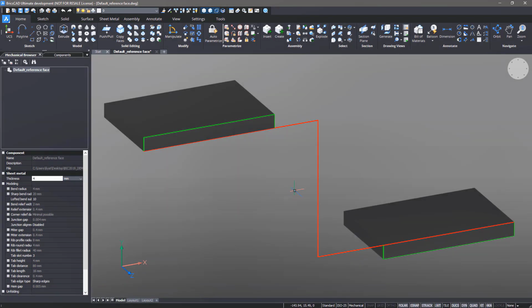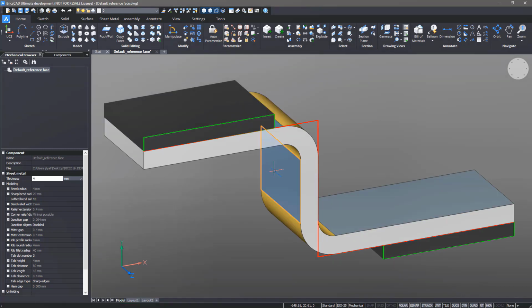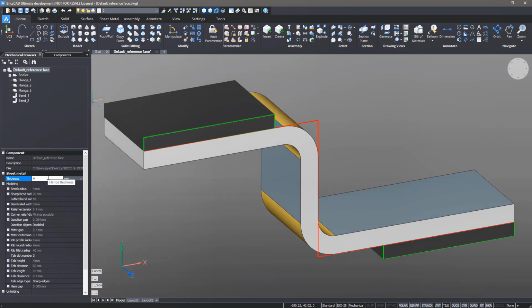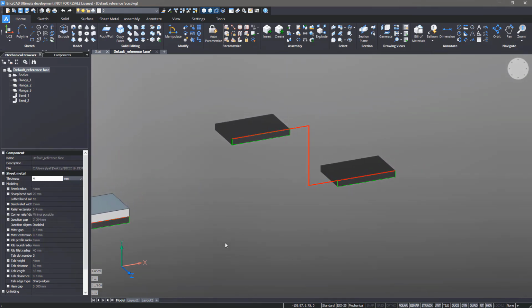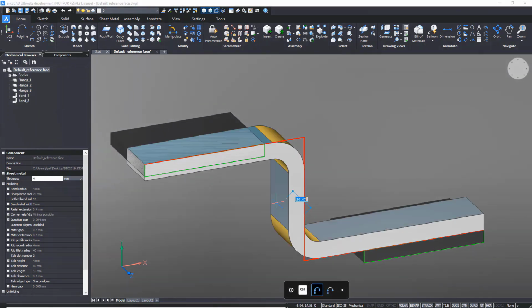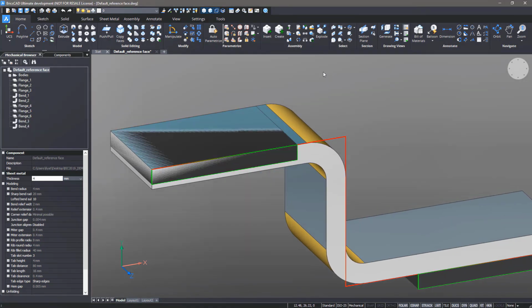In this video, we extrude the polyline to a sheet metal part, and you see it stays in between the rest of the assembly. Moreover, this behavior is kept when we change the thickness. So this is the default behavior, and this polyline is a bit different. If we extrude with default behavior, we have the collision. This is not what we want.